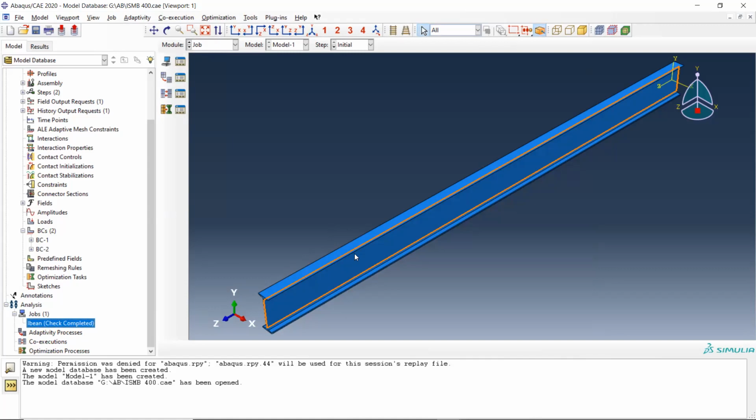Okay. Sir, in this column now, what we have to do is make it a uniaxial loading column and then go for the static analysis of it. Okay, what is the load value? Anything of our choice, sir, suppose 10 Newton, 20 Newton, whichever. Is it a tensile load or a compressive load? Compressive loads, uniaxial compressive.